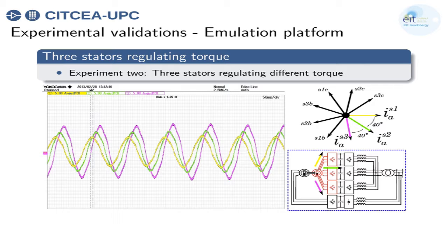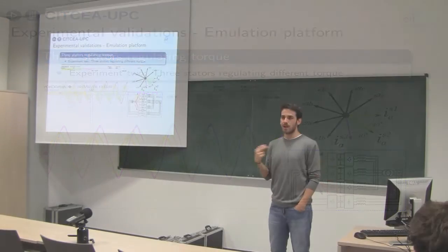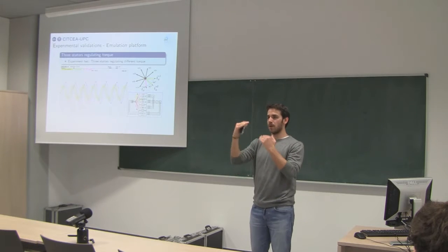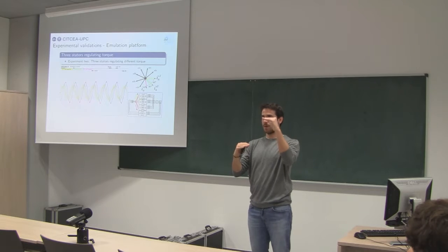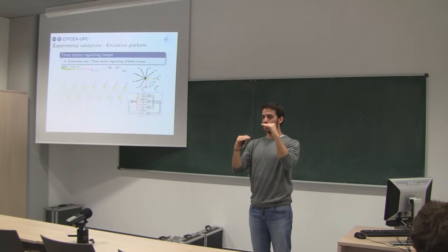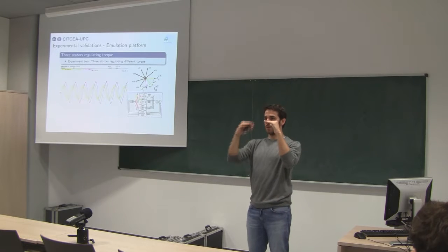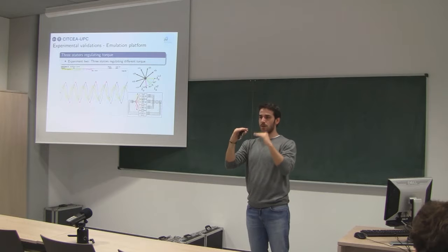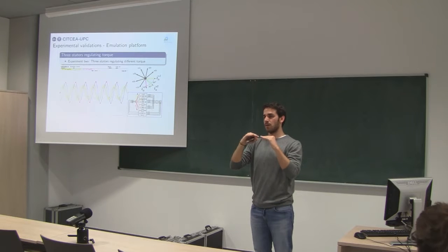You have to do a calculation on the efficiency of the system with simulation and all that stuff. So we didn't have the exact parameters of the IGBTs and all that stuff. But my feeling is that it could depend on the operational point. At some point, probably it is better to keep just one converter operating, and at some point it could be better to have 2 converters operating at low rating instead of 1, because probably if you start flowing more